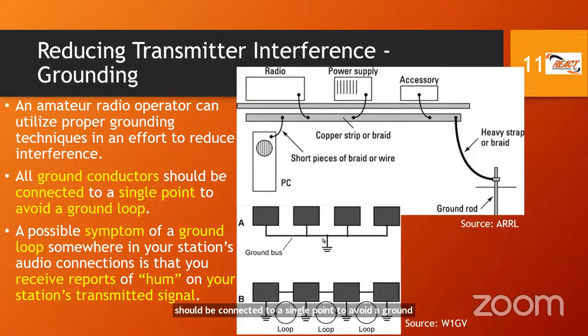And this is the ground loop here that we are talking about, we're trying to avoid. We are not grounding individually the item to a ground rod by itself. We are going to one point and we're grounding that, because if we have separate grounds, these are the ground loops that could be set up there, and you will hear a hum as a result of that circulation.